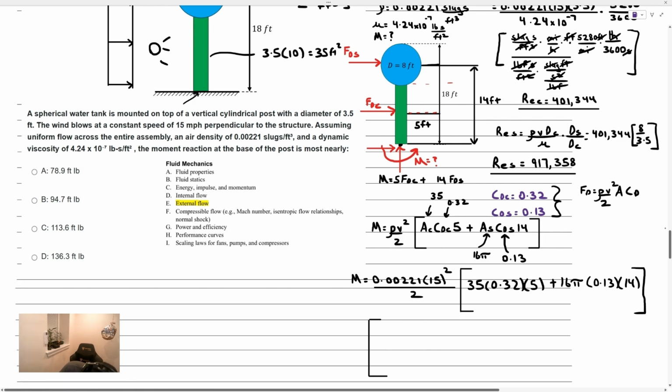The density units are in slugs per cubic foot. And of course, we have the miles per hour term, which is squared. We have the frontal area measured in square feet, and we have the moment arm measured in feet. The drag coefficient is dimensionless. You can see that the cubic feet term cancels. All we need to do is convert the miles per hour to feet per second.